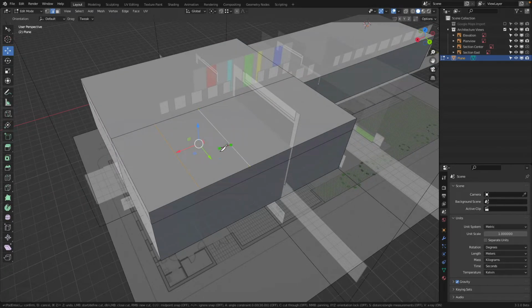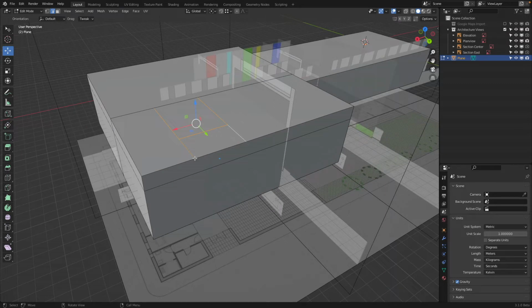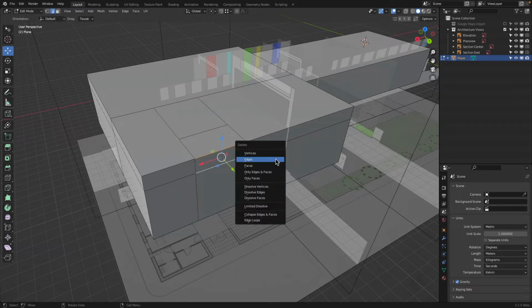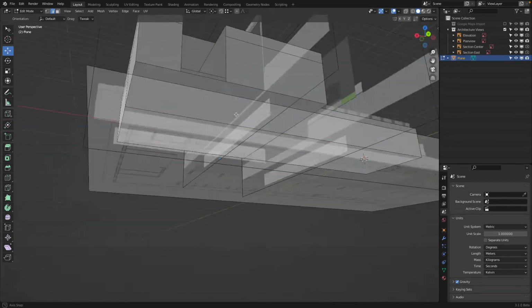K, click this one, and now I press the X key and click this edge and enter. Now this has to go down. Okay, so I can press K, click, and the Z key, and you see how this goes down, and enter. K, here, Z key, click down, and enter. Very nice. This point, or edge, I can select and delete.